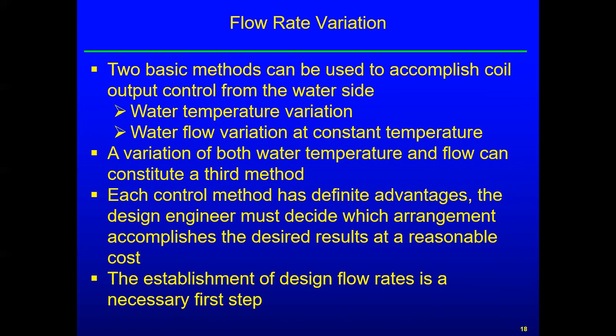You run that, you do your design. It says, okay, the worst case scenario on this zone is 9.3 tons. So you say, well, I'm definitely looking at a 10 or maybe a 12 ton coil if 9.3 is my max cooling load. So I will probably be just a little bit above that.